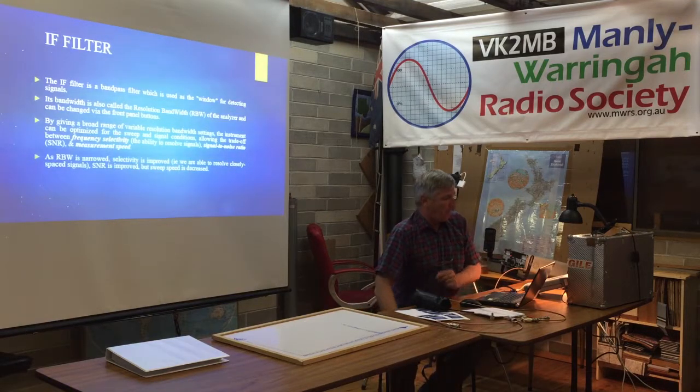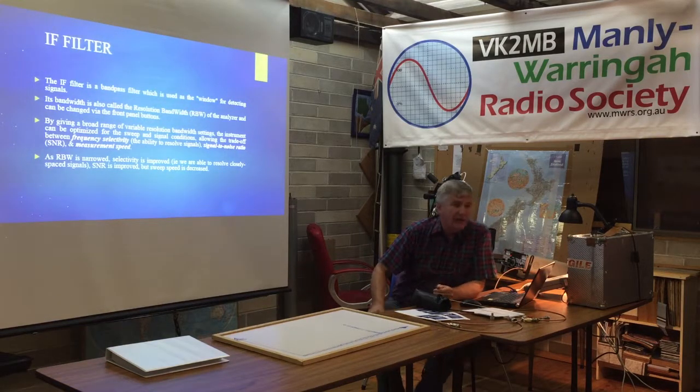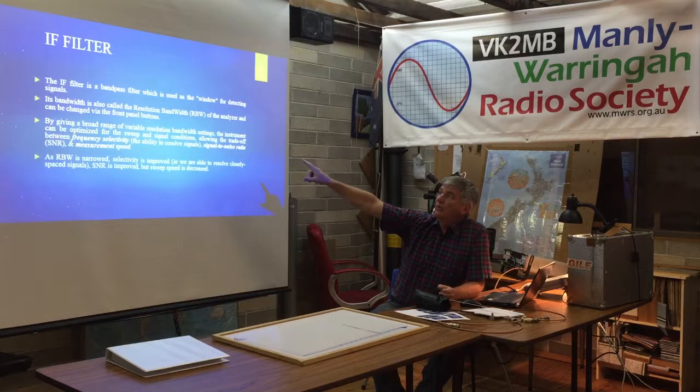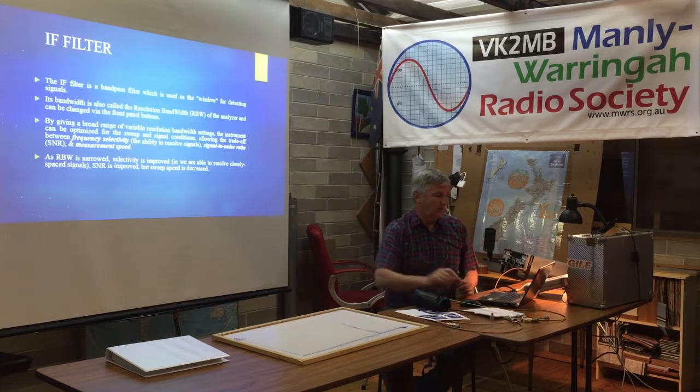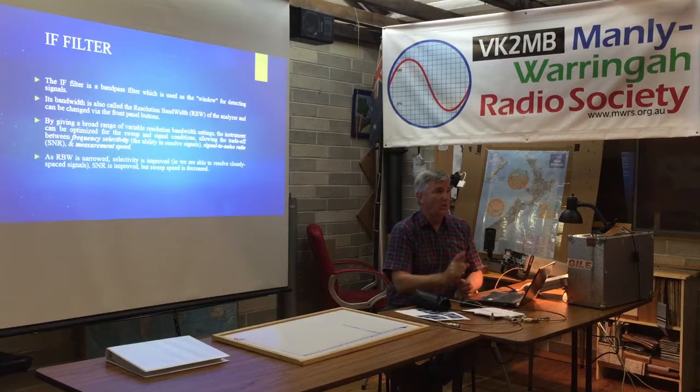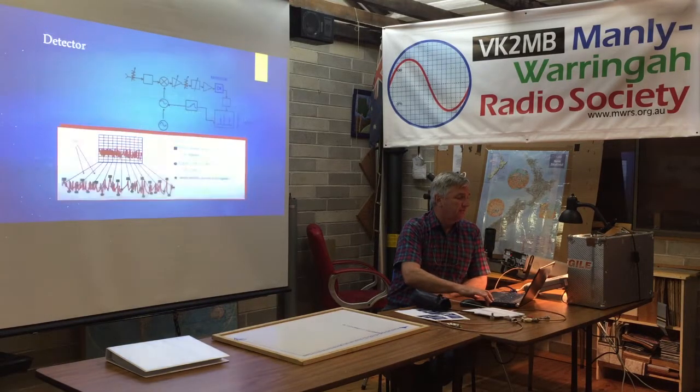So we'll demonstrate that. We'll come back to this one, but at the very end I'll do some practical demonstrations. But that's very important, the resolution bandwidth. This is where you can get yourself getting answers which are not right. So you have to be very careful about this. It won't destroy anything, but you get wrong answers. Just hold that till the very end. We'll come back to it. I'll show you in real life.